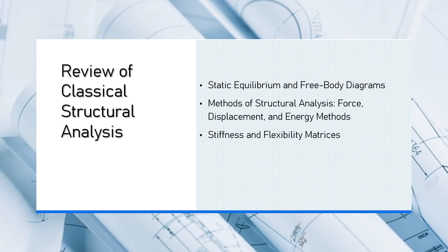Displacement methods are ideal for analyzing large and complex structures with many degrees of freedom, such as multi-story buildings, bridges, or any structure requiring a detailed analysis of how displacements relate to internal forces. Energy methods are often employed for structures that are hard to analyze using conventional equilibrium methods, such as structures subjected to dynamic loading or complex deformation patterns. They are also useful when we are particularly interested in the deflection and energy absorption of structures under loading.